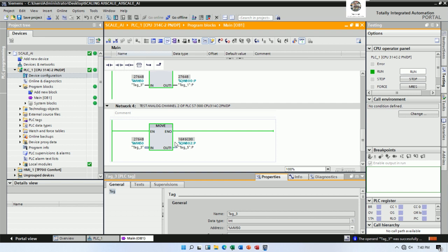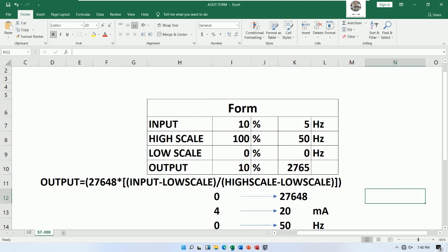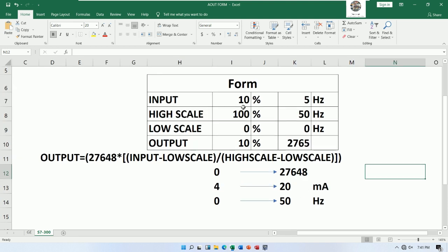So the next step, we need to convert to set point. Example here. Example, we would like to set from 0 to 100%, and it is the value. Example 0%, it will show 0 for raw data, and the value will show 0, and the milliamp will show 4 or 0 milliamp on the multimeter, right?